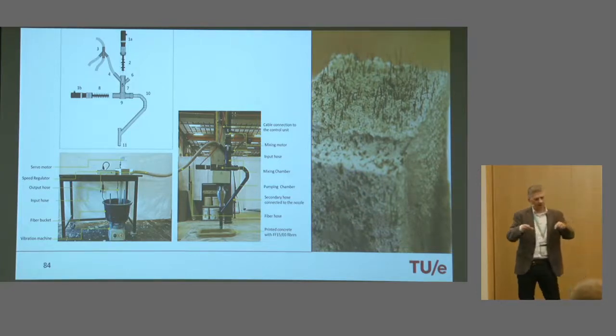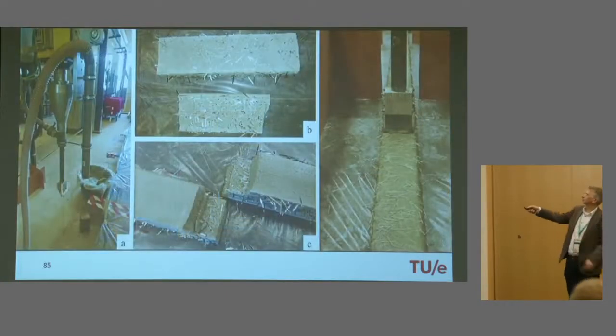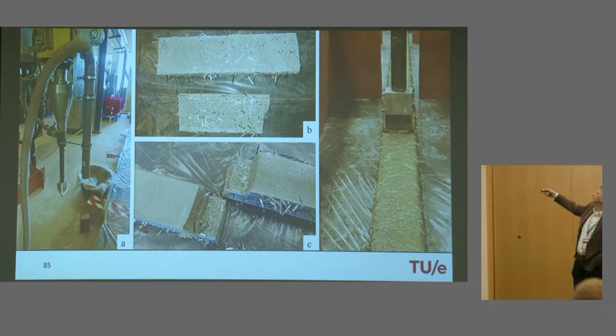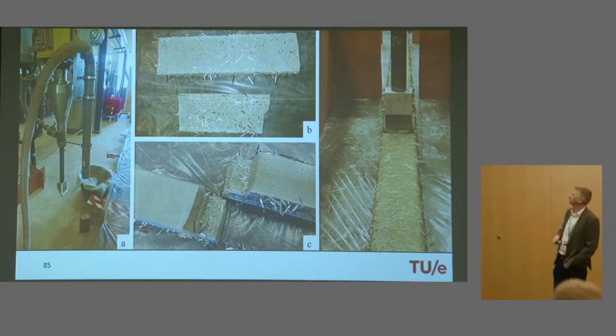But do realize, only in the filaments, not in between. But you can sprinkle in between. So if you print, during printing, you can just sprinkle up front or at the back of your nozzle and bring fibers in the interface at the same time. Yeah? So there is an option to have fibers everywhere, in your filaments and in between your filaments. And we tested that, of course.